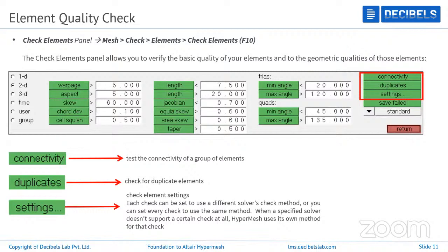You can see in the bonnet, one large component is there, that is huge, made of steel or aluminum, having very few features. When it comes to the interior panel, it is made of plastic or fiber components having more features. The clips will come, any pressing components will come, sockets will come. That means it has more features, even though it is plastic. So meshing the bonnet is easy compared to the interior panel. Why? Because of the geometry.